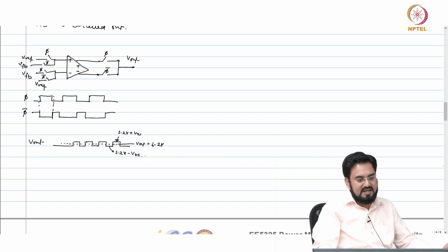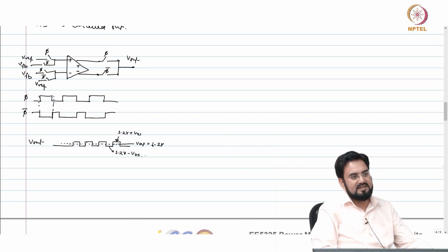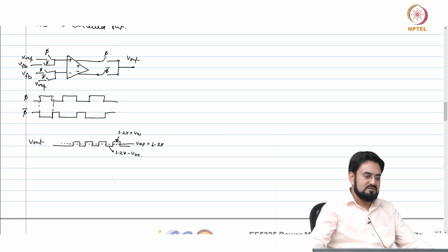Okay, so most of the time we combine the two techniques. You first do the static offset cancellation, bring it down to whatever you can easily do with the design, 1 millivolt or so, and then on top of that you apply this dynamic offset cancellation.